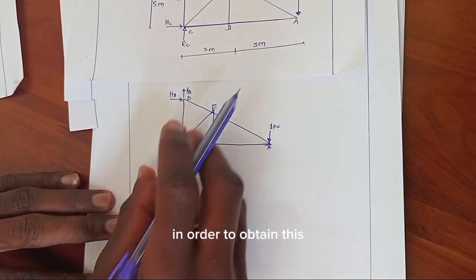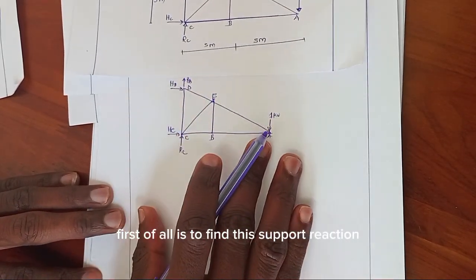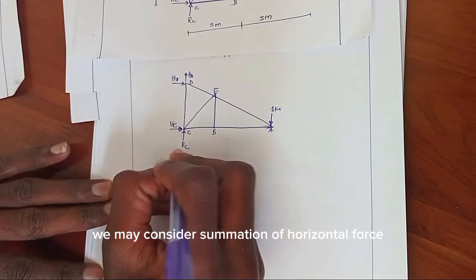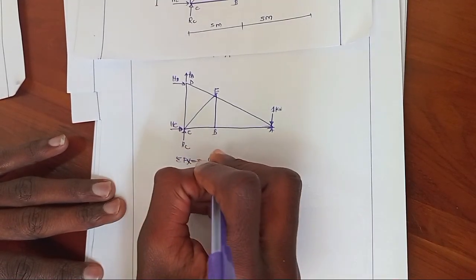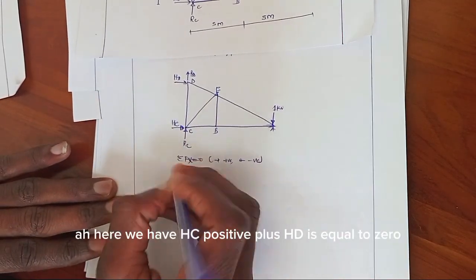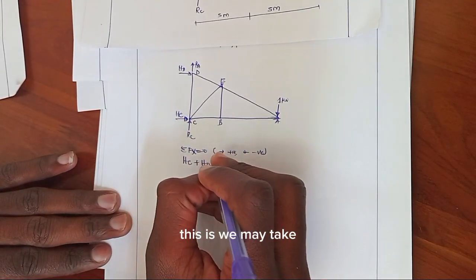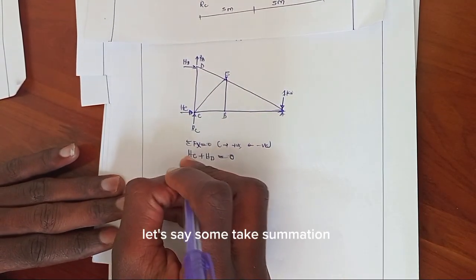Now, in order to obtain these normal forces, first of all we need to find the support reactions. So, in order to obtain these support reactions, we may consider summation of horizontal force equal to 0. Positive, negative. Here we have HC plus HD is equal to 0. We may call this equation number 1.